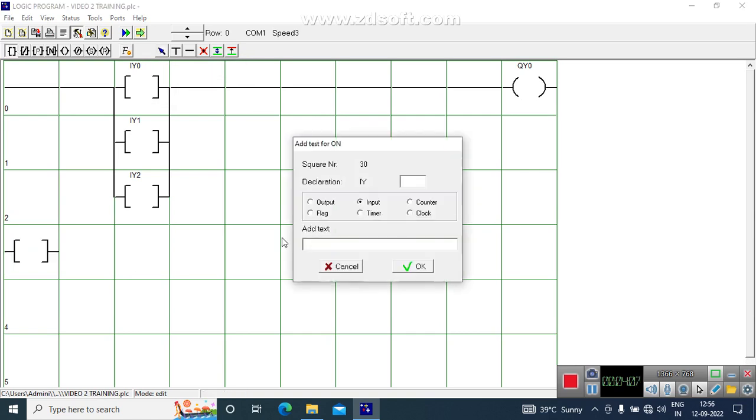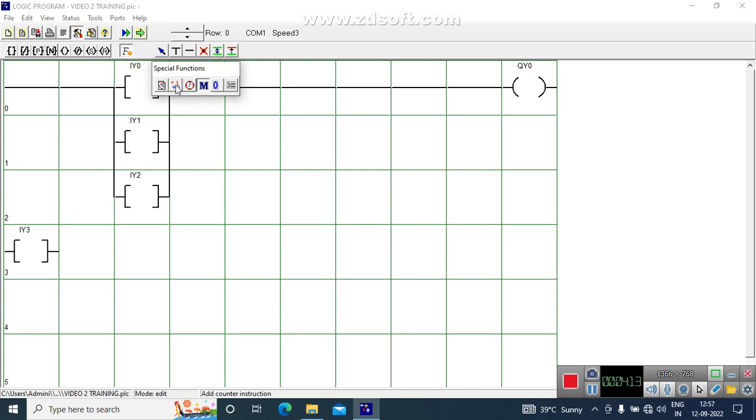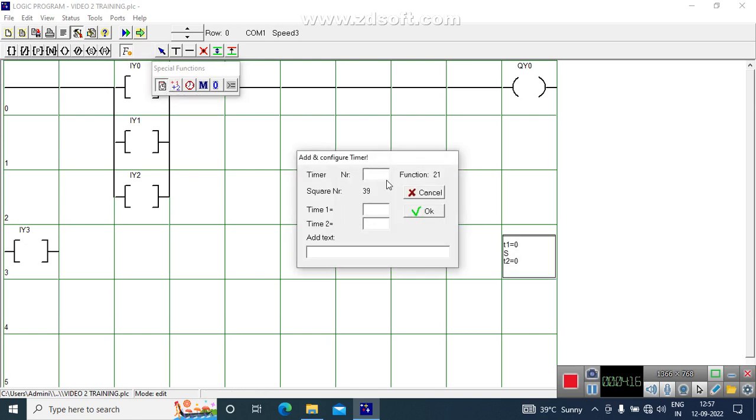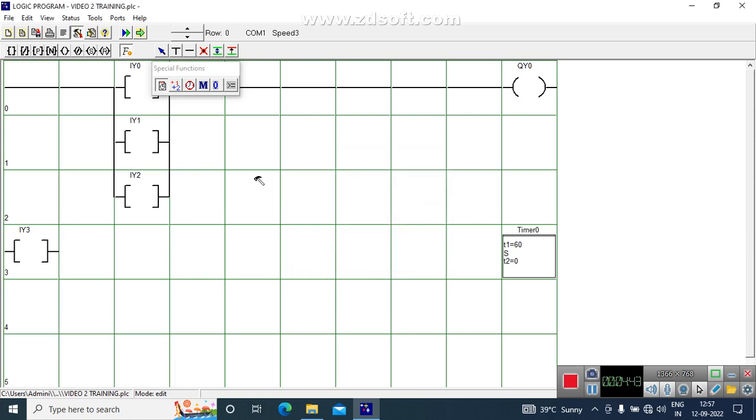now we'll start with the timer. Say input 3 and function timer. So timer number 0. Now as you see here, there are up, time 1 is time up, time 2 is time down, or we can have both types here. So let's start with time 1, time 1 number. So time number 1, which is a time up count. If you use time 2, it's a down count. So we make this here, and we now connect this input 3 to timer, and we run the program.